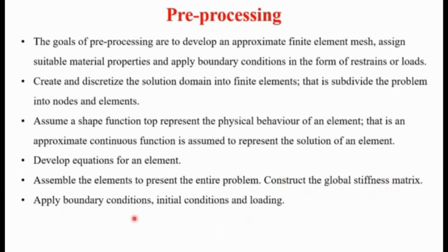Then apply boundary conditions, initial conditions and loading. Boundary conditions means loading, different types of loads. Then again constraints, some constraint that is fixed or cantilever type of the beam. So again we have to apply these boundary conditions in the pre-processing phase only.